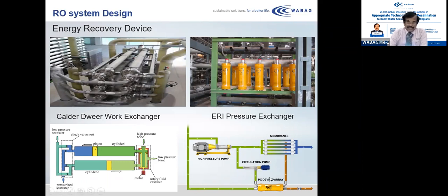You can see that this pressure exchanger is located in the brine system. So the brine water comes in, and it does not have any valves. It enters the port, and when the water at low pressure enters from the other end and pushes to the other end, by the time it comes to the other end, the rotor changes its position and comes to the discharge port opening.